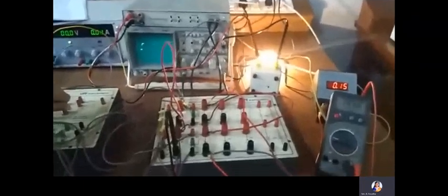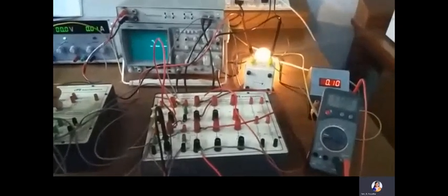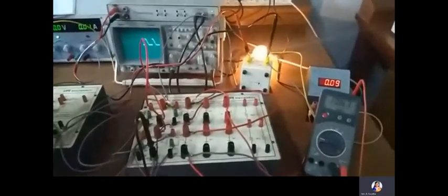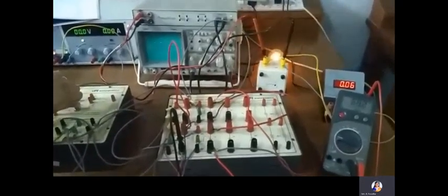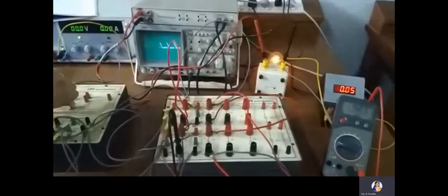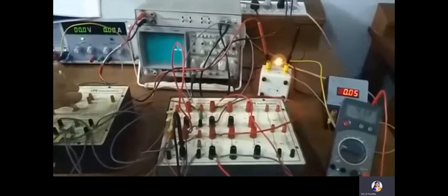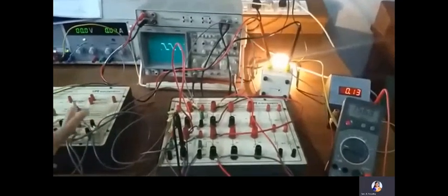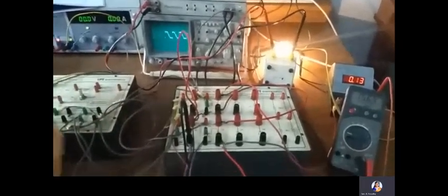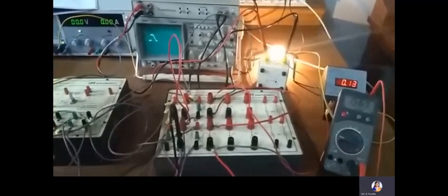Now as I increase alpha, I kept alpha at 45 degrees, the output voltage is 184. Alpha I have kept at 90 degree, the output voltage is 111. I increased alpha to 108 degrees, the output voltage is 75. And alpha is increased to 36 plus 90, now the output voltage is 42. Like this you can vary the value of alpha and note down the voltage across resistive load in case of fully controlled rectifier. And I want you to draw one waveform for any value of alpha.